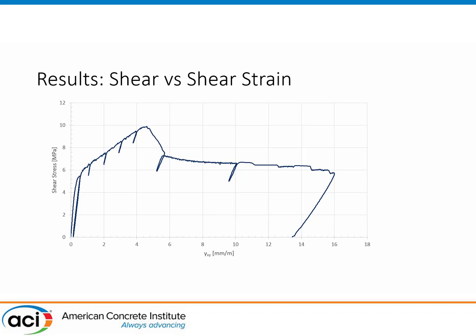Also, if you note carefully, each one of these unloading cycles where we took the photographs, we had to unload to make sure it was safe. Of course, almost no creep actually during the unloading cycles. But if you look carefully, you'll see that the slope of these unloading segments keeps on going down as we go up. That's because as new cracks form, we end up with more elastic behavior coming from the fibers and less from the concrete. And so there's a transition as things get softer.